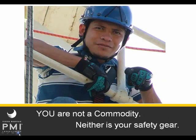Any rope that is intended to support a live load will clearly be identified as being a life safety rope. Commodity ropes such as clothesline, tie-downs, or hardware store rope should not be used for life safety purposes. That sounds like it really ought to be a foregone conclusion, but believe me, it happens. Be sure that your rope comes from a reputable manufacturer. It should be properly labeled according to its use, and the label should clearly show test results such as the strength, diameter, elongation, things like that, as well as how to reach the manufacturer in case you have additional questions.